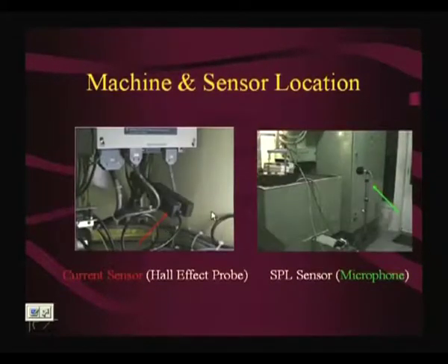We also have some current sensors. Current sensing is very simple compared to force sensing. As we shall see, we wanted to see whether, rather than using a force sensor, we can use a current sensor and then estimate the wear, so that we can find a technology which is implementable much more cheaply than a force-based technology.